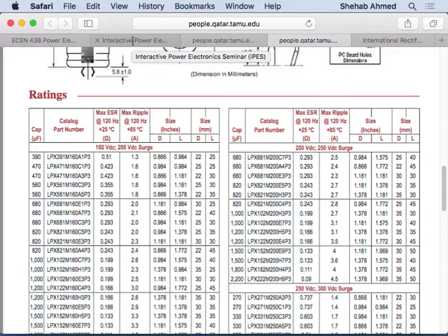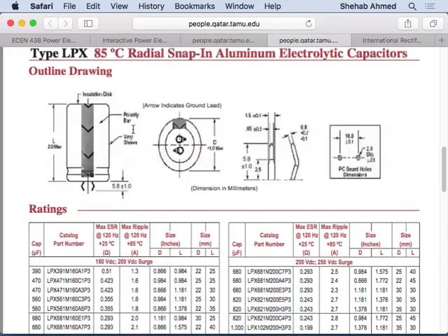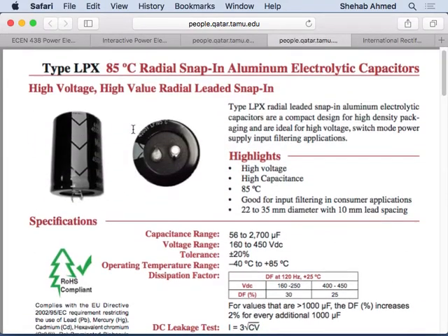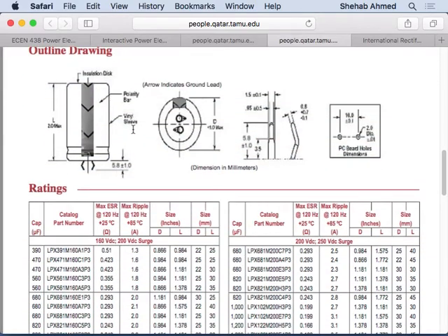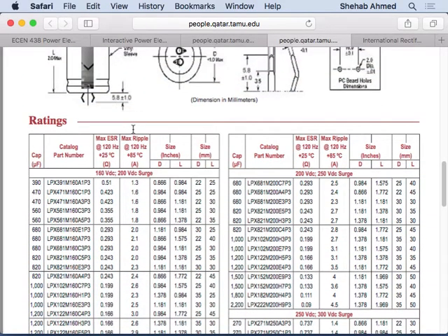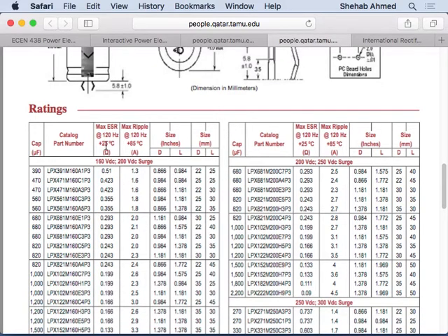But why would they include the value of frequency here? Why do you think it's important? Yeah, in an application like in an electrolytic capacitor, this is an electrolytic capacitor data sheet. Electrolytic capacitors, we said they typically give us large capacitance values, and we said they're very poor with ESR, so they have a very high ESR value, and they give you here the ESR at 120 hertz. Why would that be important?